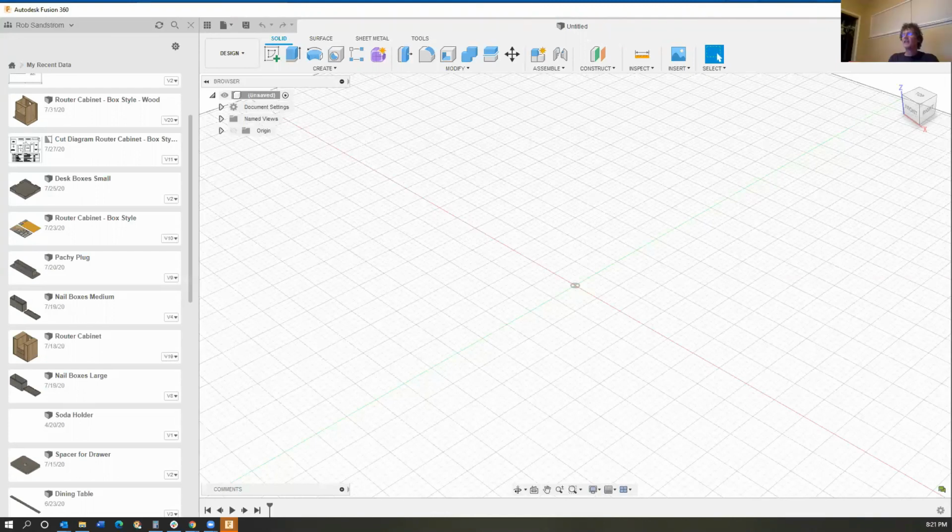I can just open up the SketchUp files. It takes 2019 and earlier files. So you have to go into SketchUp and save it back as a 2019 file, and then it'll come right into VCarve. In fact, VCarve will nest your project for you and everything if they're all the same size. Or Aspire, VCarve Pro, either one.